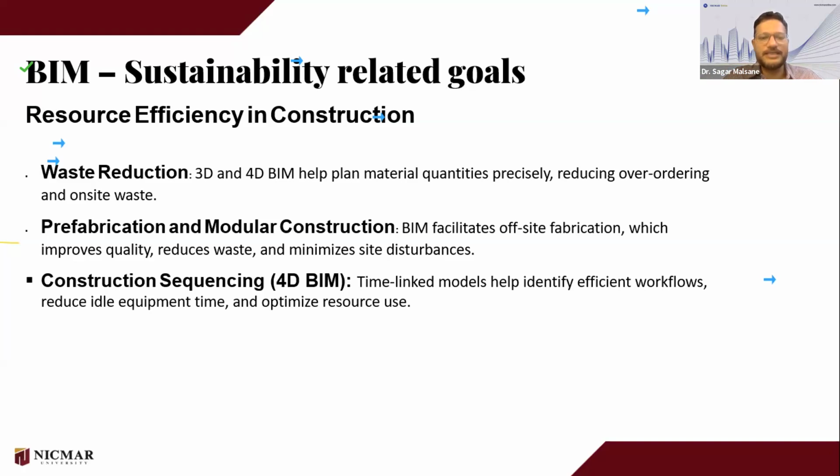Then through BIM, prefabrication and modular construction can be facilitated. So offsite fabrication really improves quality, reduces waste, and minimizes site disturbance. So that can be done through BIM, and the 4D aspect of BIM, which is about visual scheduling, really helps construction teams to visualize the sequence of workflow, to identify bottlenecks, to understand idle equipment time, and strategize for better resource utilization.